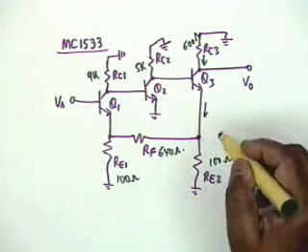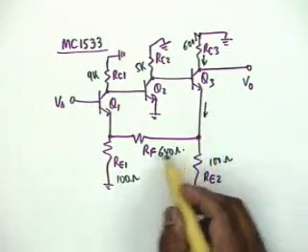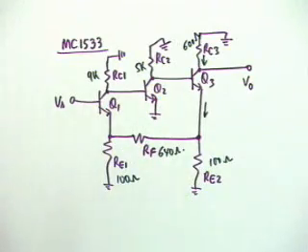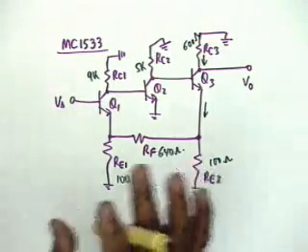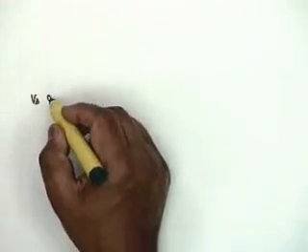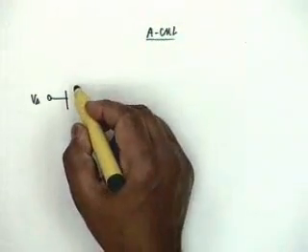Okay, this also we are acquainted with. This is a very standard method, particularly in IC configurations. So it's a current sampling, and obviously there is a voltage comparison, and therefore this is a series. Now, without bothering about any of the steps and the rules, with a little experience, one can draw the equivalent A circuit and the beta circuit. The A circuit, if you look at it carefully, I am drawing right by inspection. It would be the following.